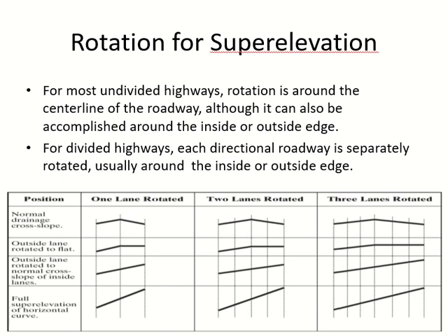And so this is how it will happen. This is rotation with reference to center. Let's say this elevation is x. From here, this is normal, right? And this is full superelevation. So from here to here, the center will remain x. Now you can see this one. If this one is, let's say, y, from y it goes to like this, changed. Again changed. Now you say increased, right? More increased. So y is changing. Same thing for the inside edge, because the reference is center. So inside edge, less, more, less. So the other edges, the elevation will change. The reference will remain constant. Clear? Okay.